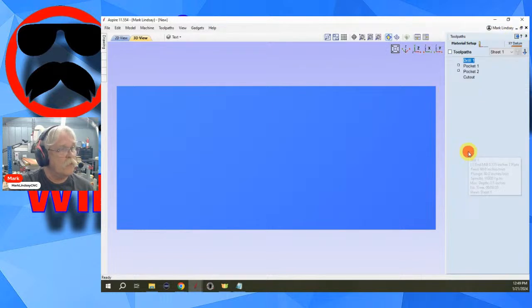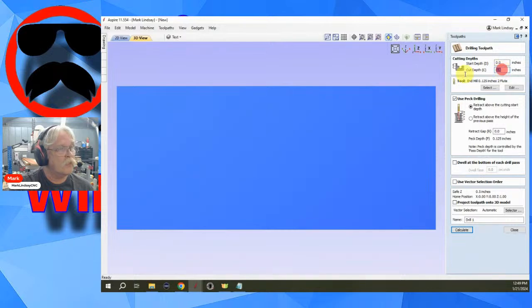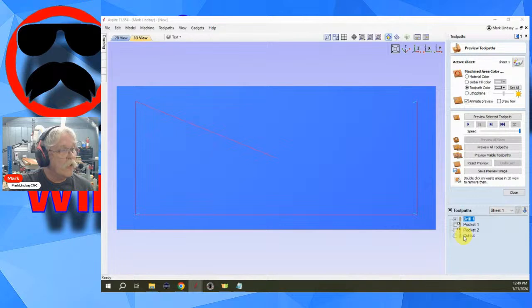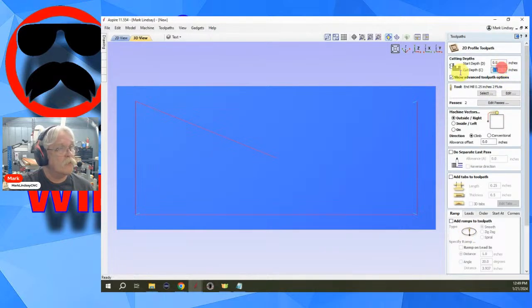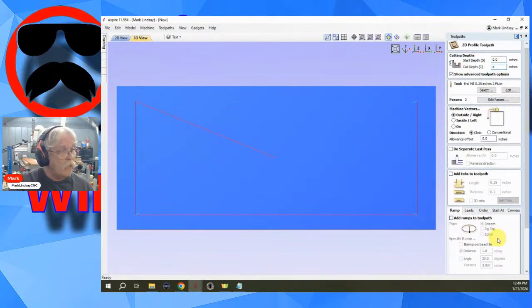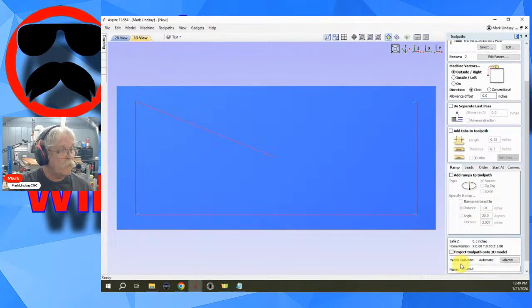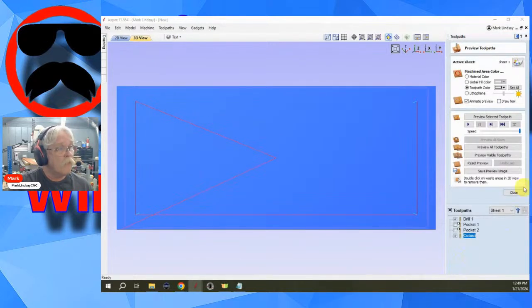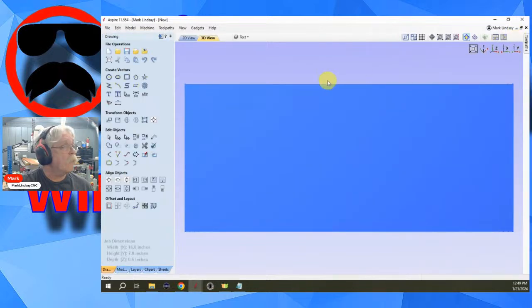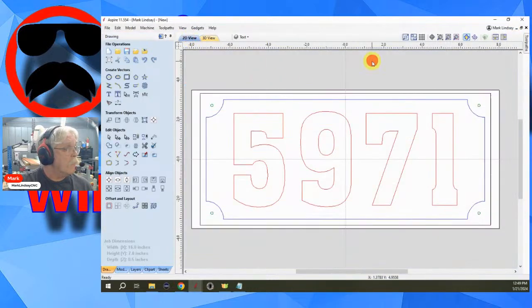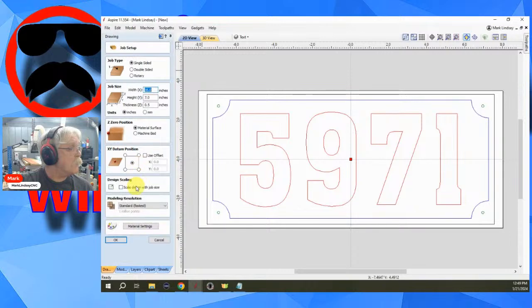And let's go into these two toolpaths, and we'll just type Z, calculate. Then we'll go into this one, and we'll type Z and calculate. All right, close. Let's uncheck these. Close. Now I want to go back and change my job setup to where it's 1 inch, just because I've not used that number yet.